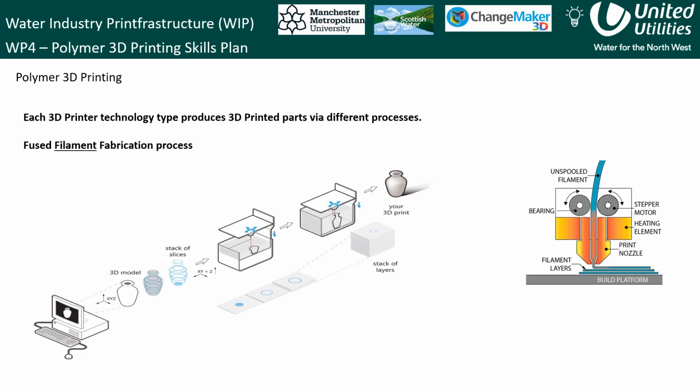Next, the 3D model is imported into the slicing software for each 3D printer, which is commonly bespoke to each printer brand. The slicing software then turns the 3D model into slices, acting as layer-by-layer instructions for the 3D printer to follow. There are a number of settings in the slicing software that you can change, including infill, part orientation, layer height, and many more.